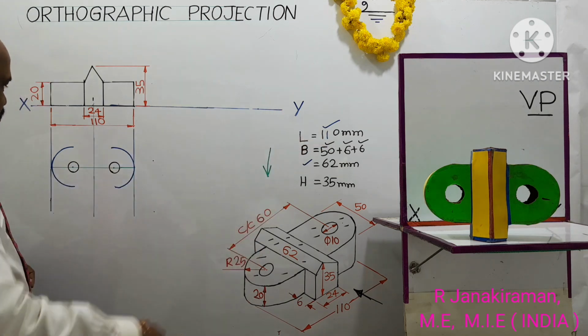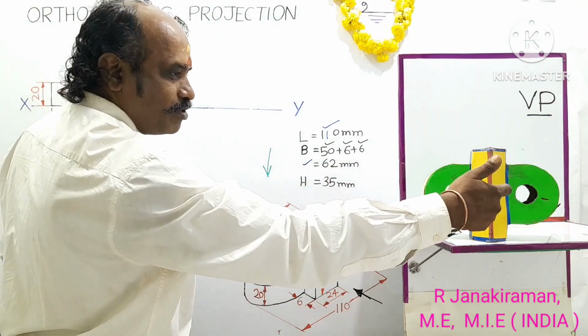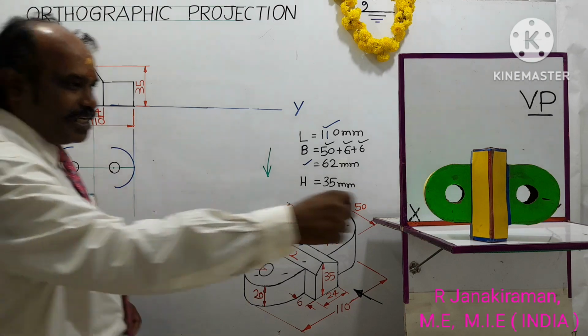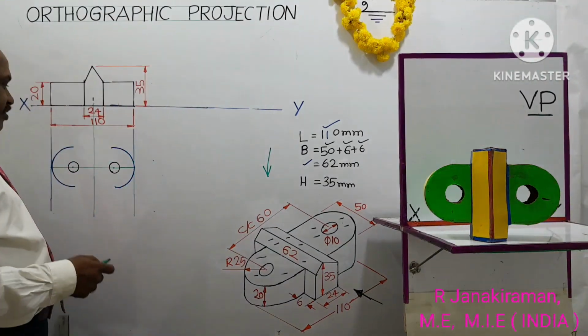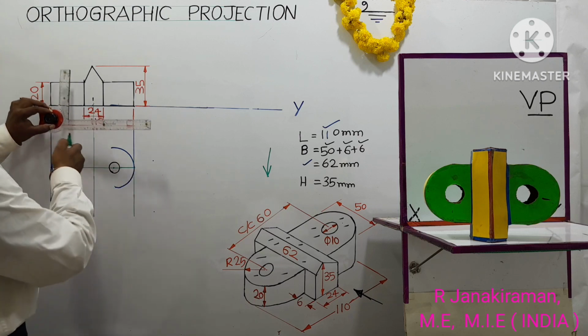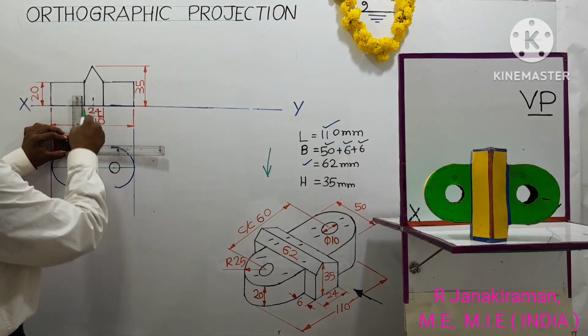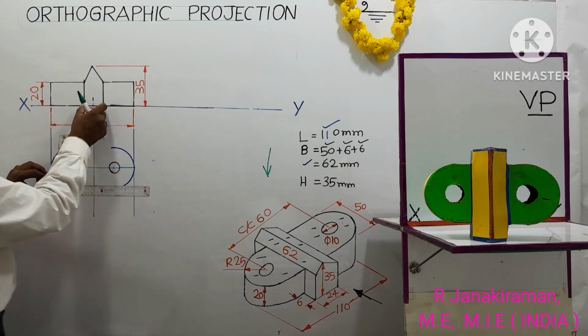The green portion is to be completed. At the center you can find this yellow surface. The small yellow surface seems to be a rectangle whose linear distance we don't know, so we will project it from the previously drawn front view. Project from this previous front view using a 2H pencil, this edge, one on the left and one on the right side. This 24 mm gap is projected.